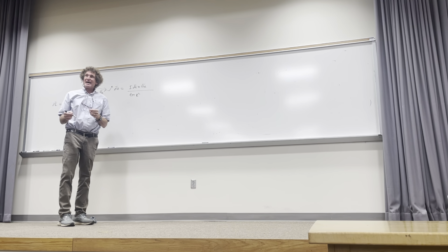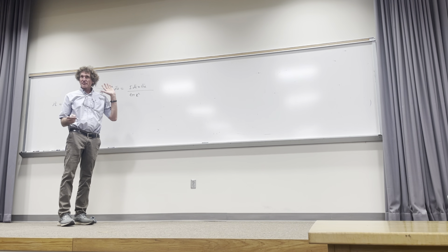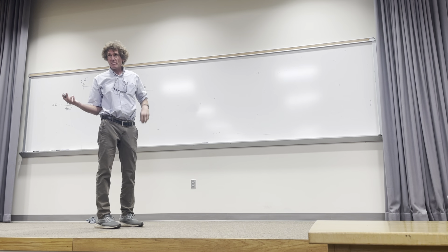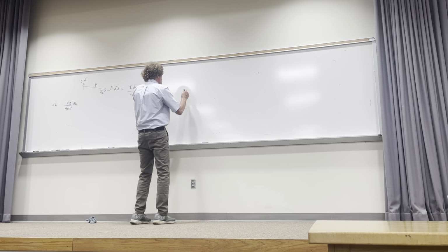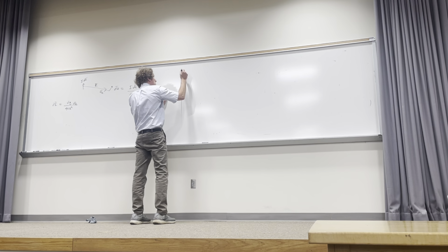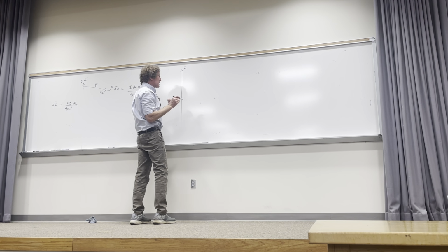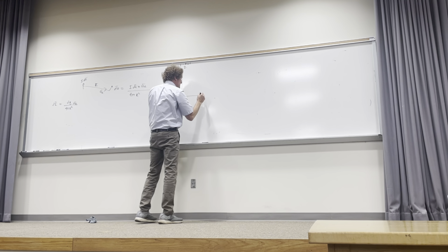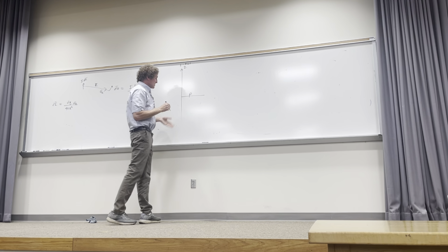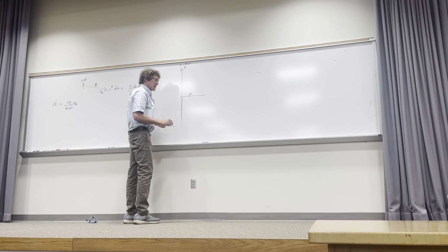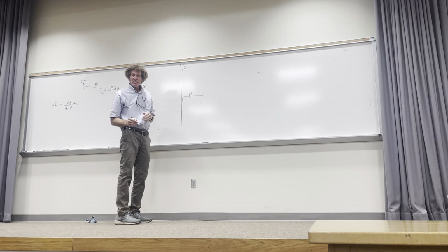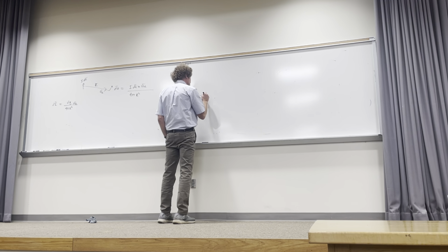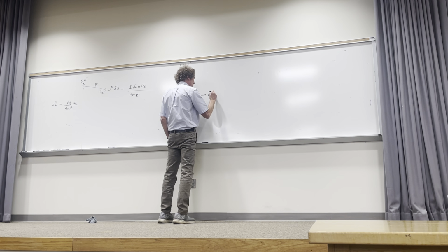So now an application of this to an infinite line. This is a classic problem. So you probably did this in physics, whether you remember it or not, another story, but it's a classic. If you have the z-axis here, you have a current I that doesn't vary on the z-axis, and I come out a distance rho away. Now the book here assumes it's infinite, but it doesn't have to be infinite. It can be semi-infinite, or it can be from any position A to B. And I want to know what this differential H is right here.